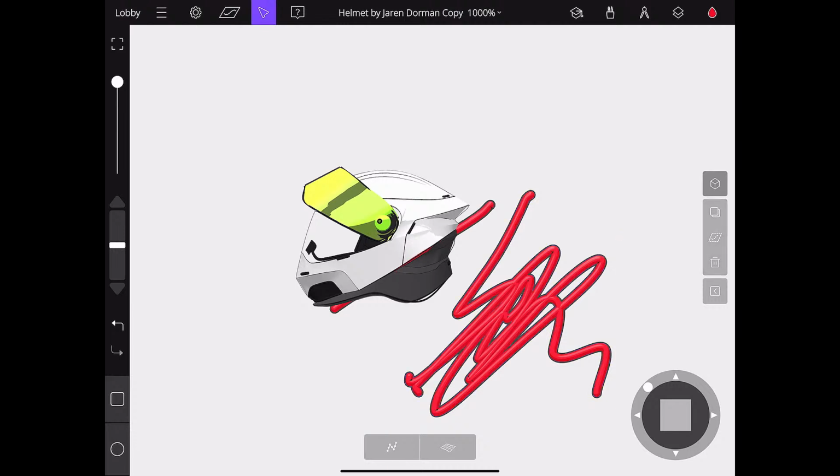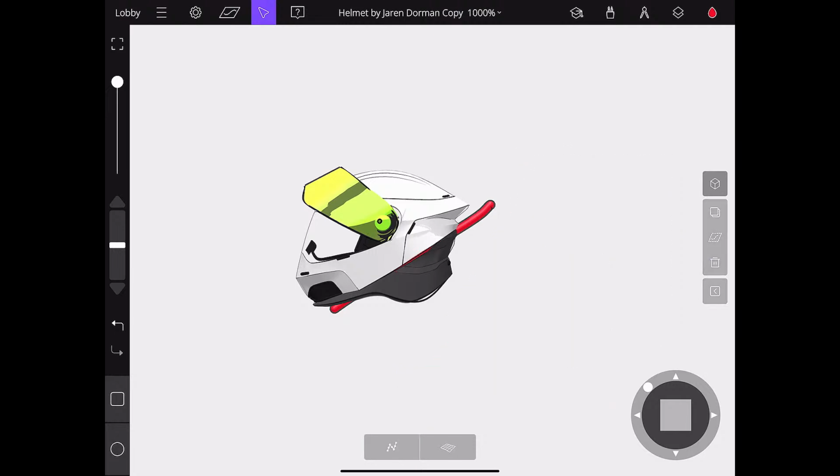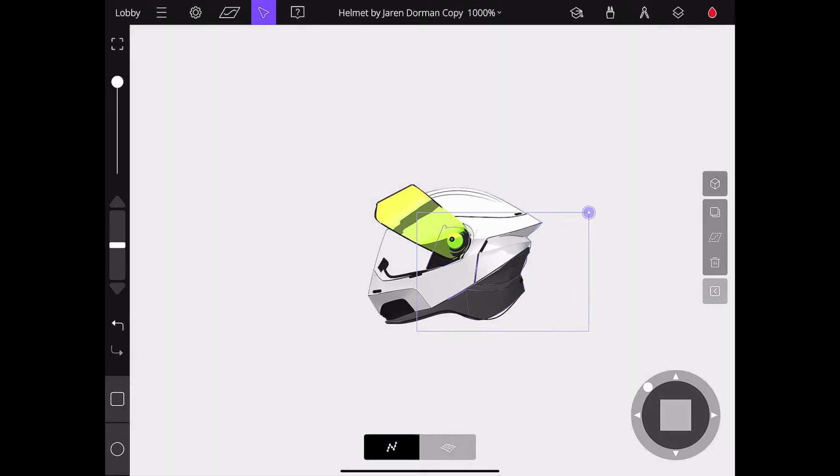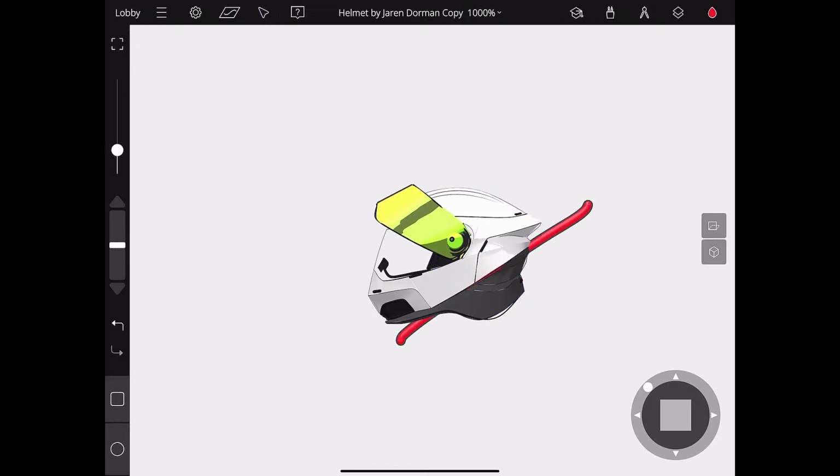Oh, by the way, earlier I was trying to remember which it is as far as the box select goes. If it's left to right, if it's inside the box, it will select it. If it's right to left, anything the box touches will be selected. So, little tip there. Anyway, yeah, so if we're in a side view here, I'm just going to draw.